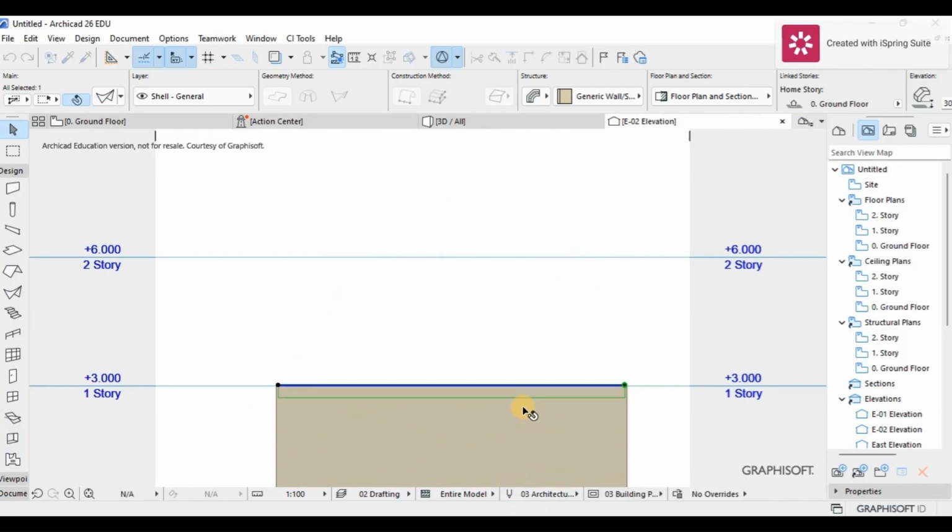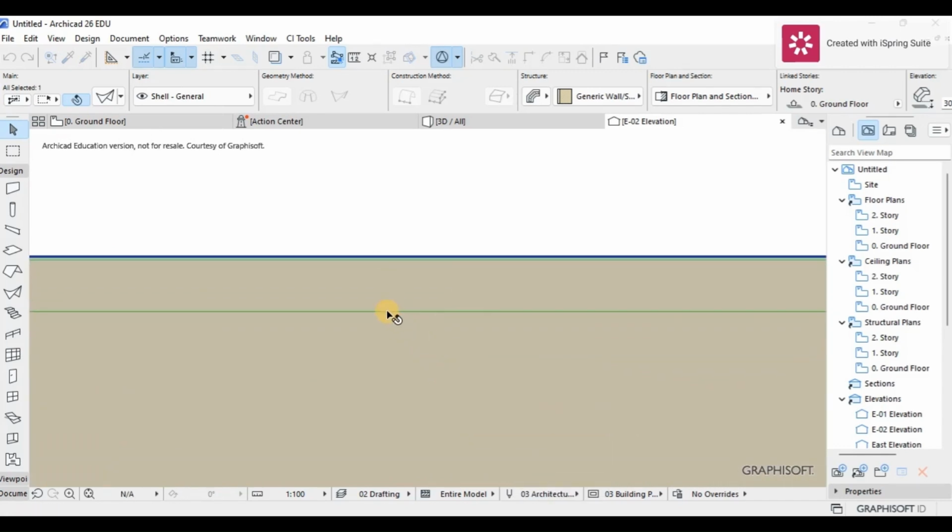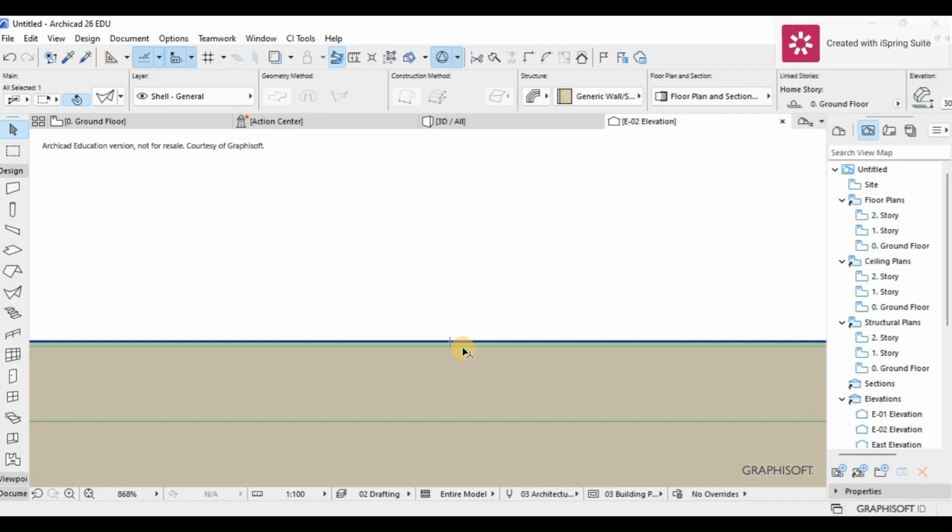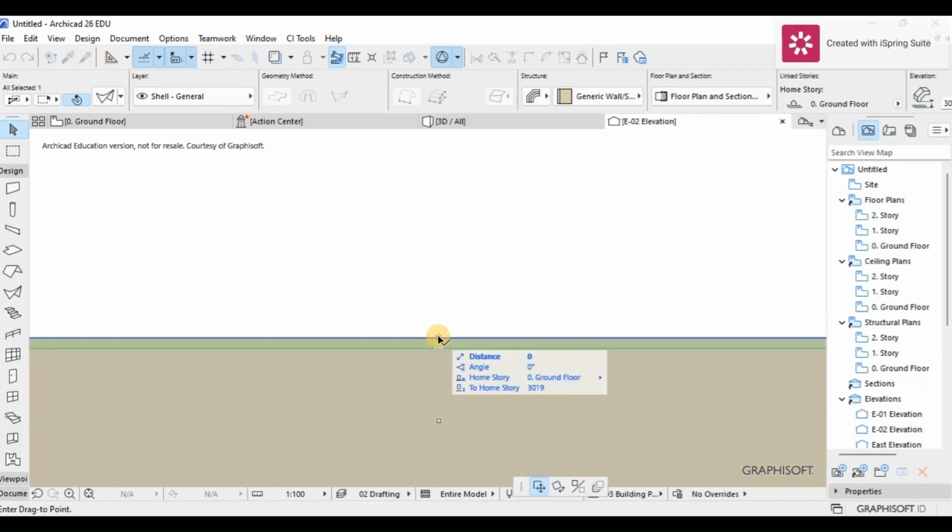So that done, I can now make this thing flat again. Select there and select the flat option. And then you see it starts as a straight line. So I can start at the middle and draw the first portion of my gambrel. Come here and let me just zoom in so that you can select the blue part.